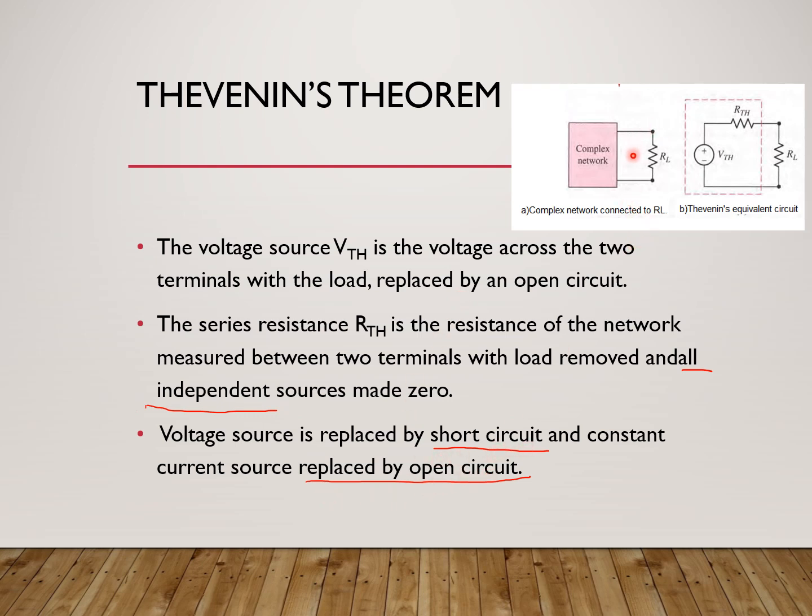Once you do that, find the equivalent resistance at the load terminals, with the load resistance open circuited. This is your RTH.